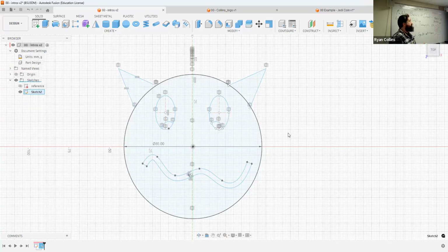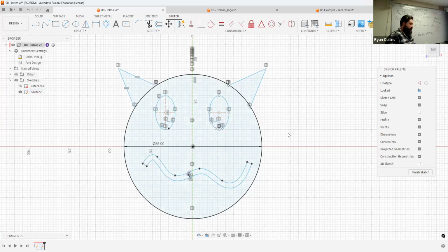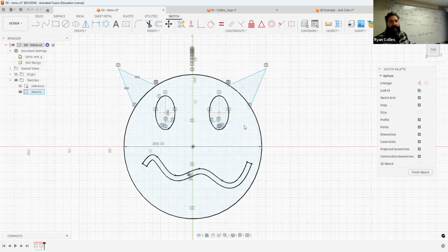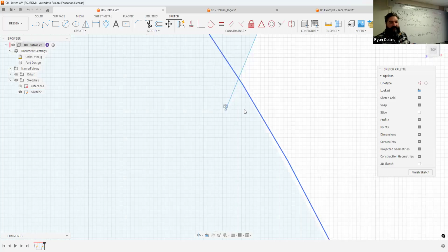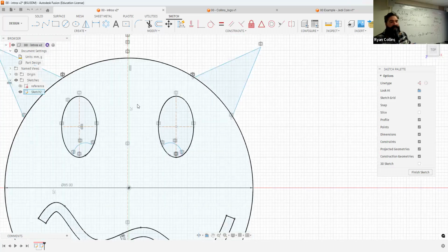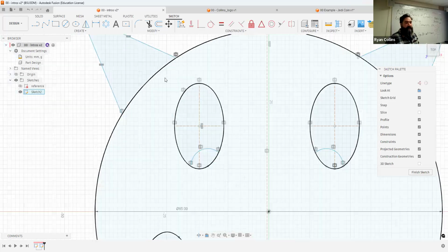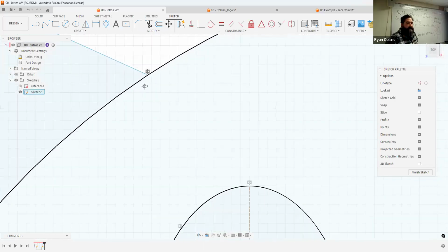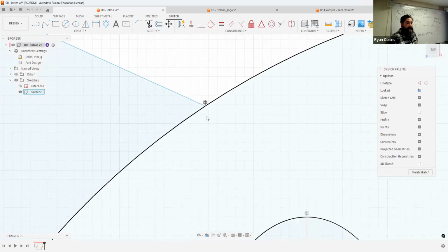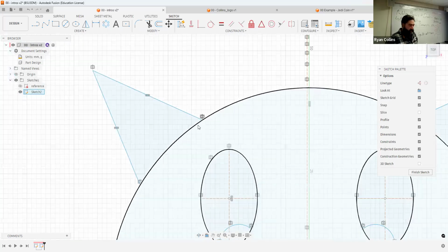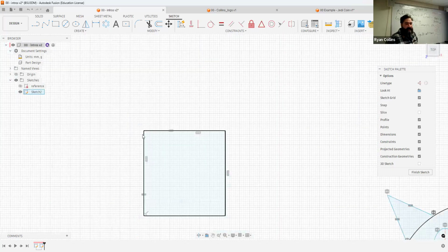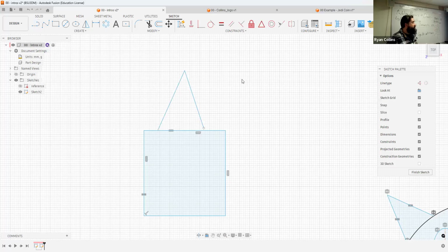That brings you back into the sketch environment. You are actually altering your existing sketch. At that point, I highly recommend zooming in on things. If you are seeing a section that isn't quite closed, this does get very tedious, admittedly. Like, where the hell is the break? I can't find it. So let's just use this over here as an example. I'm just going to draw a bit of a line up, and it's super close, but it's not quite closed.